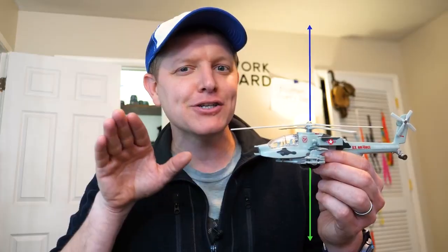Neil goes on to explain that in the 60s they were thinking about the problem of descending to the surface like hovering a helicopter, so that's where they started. The problem with a helicopter, though, is it changes the way you move laterally. Let me explain. If you think about a helicopter, it has to offset its own weight, right? So if you've got the weight here, then you have lift that's pulling it up at a certain amount to offset that, right? If you decide to translate forward, meaning you want to tilt the helicopter forward and move in that direction, you still have a vertical component of lift that's going to offset that weight, but you also have this horizontal component that will let you accelerate forward.